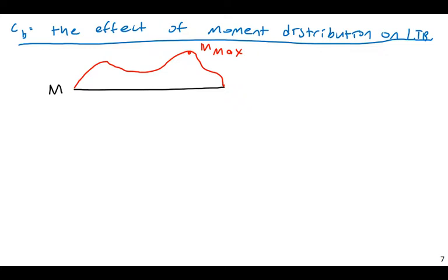Now, in terms of plastic moment design, that is perfectly valid. In terms of plastic moment design, that does make good sense because that is a phenomenon that occurs at one particular location. But lateral torsional buckling is more of a buckling failure.